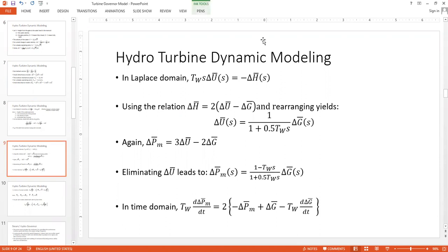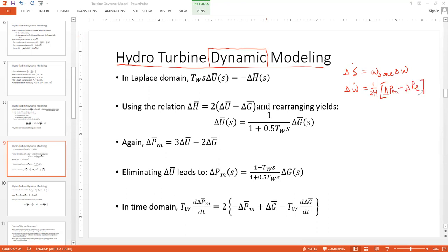That means before we considered this hydroturbine dynamic model, before we introduce these dynamics into our system, we had something like this: omega dot, that is the nonlinear model, of course, and the linear one would be like this: omega base del omega dot was 1 upon 2H (del PM minus del PE), del EQ prime dot, 1 upon TDO dash, delta EFD minus delta EQ.